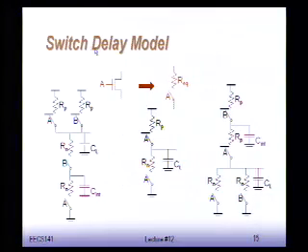Okay, so now, here's what we do. We take a CMOS logic gate. In this case, this was an AND logic gate, as you can see. There are 2 parallel PMOS and 2 series NMOS transistors, and we replace it with the switch and some capacitance, okay? Each of these capacitors you would calculate is basically a combination of gate capacitance and drain capacitance.